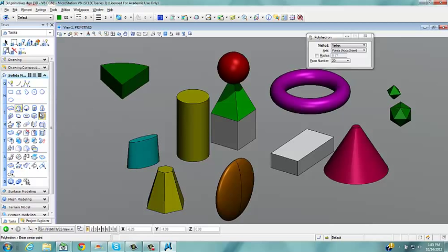Now, these are all primitives. We've gone through that. And modifying primitives utilizes things that are all part of Boolean operations. If I want to, for instance, make all of this shape that we created here one particular object, under this T menu we have unite solids, find the intersection of solids, or subtract solids, or find the difference between solids.